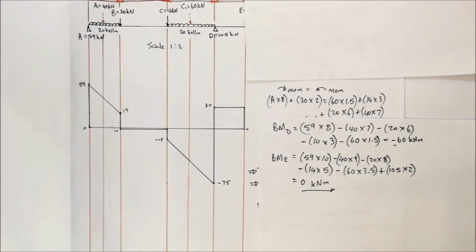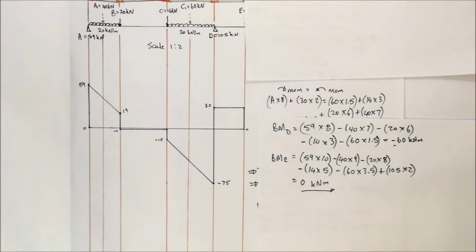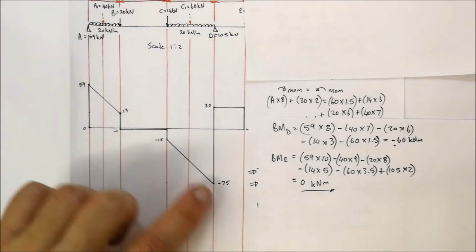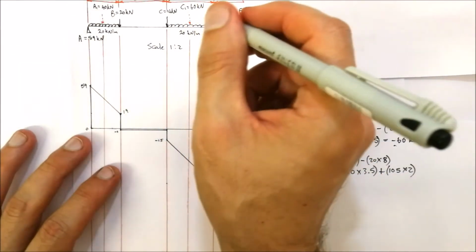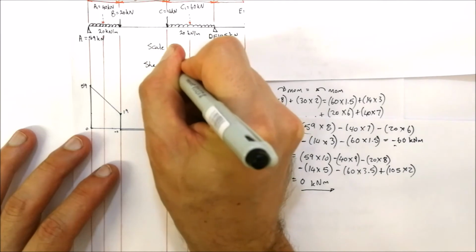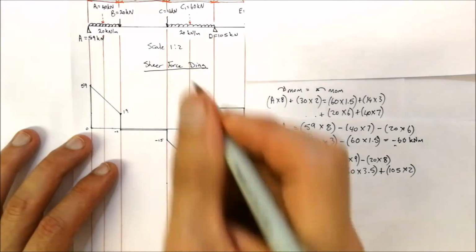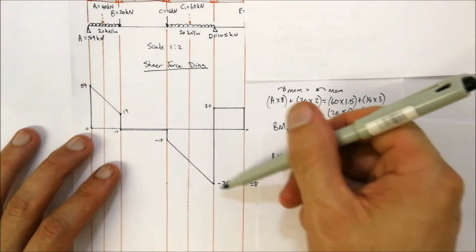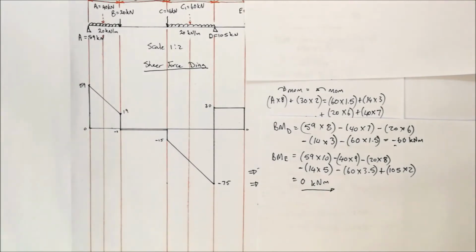Alright, so now that we've looked at the bending moments and done these calculations, we've got to take 2 points into account. Essentially we've got these points A1 and C1. Because with distributed loads, the bending moment is not a linear line as we've got with our shear force diagram over here. When it comes to bending moments, it's not a straight line. It's a curve, so it's always a good thing to have another point.